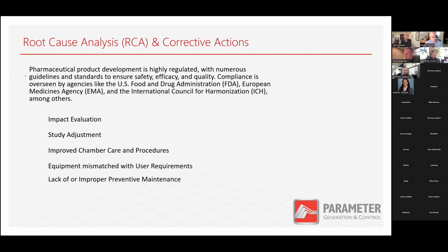Yep. And beyond the backup room, Walter, we do have several systems that are just fully redundant units that speak to each other and monitor each other. If one unit has a heater failure, the other unit's notified immediately and begins to warm up and transitions to take control of the room. The customer gets a notification of a failure. The room never experiences maybe even an out of spec condition.